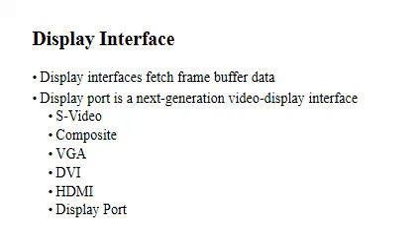Then Composite. Composite or RCA has the lowest quality signal, but it is okay for video transfer. Another type of video cable such as RCA sockets with much higher signal quality is component video connection, which has separate RGB cables. They are not widely used.